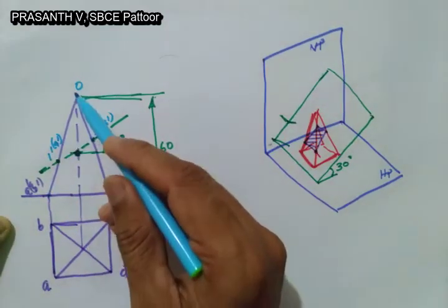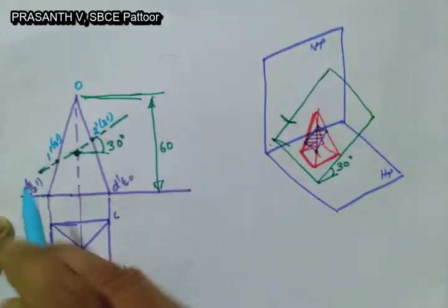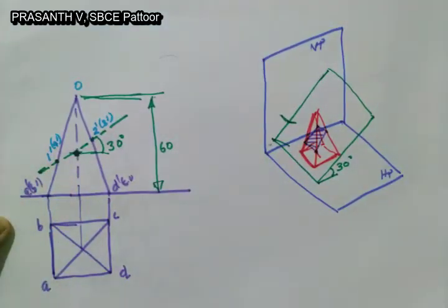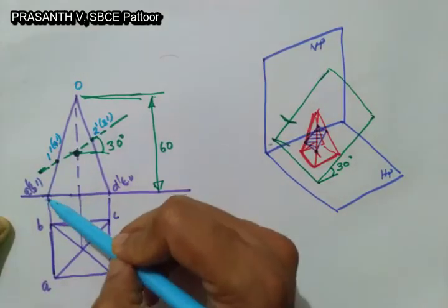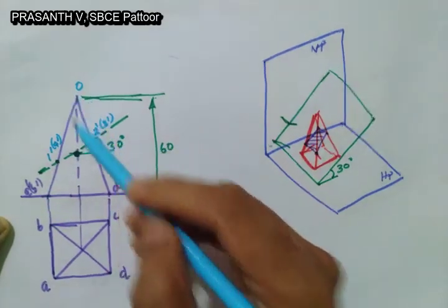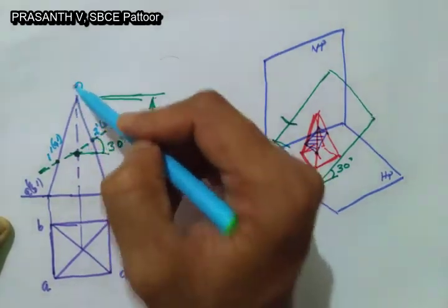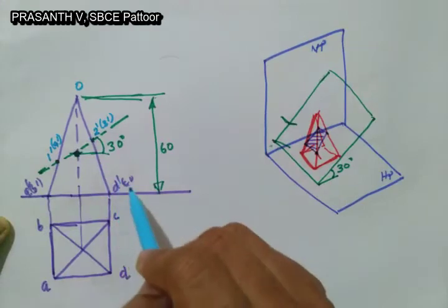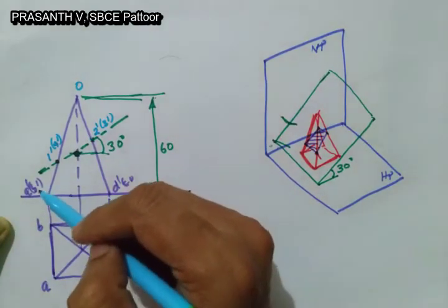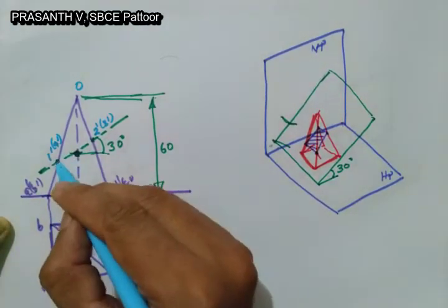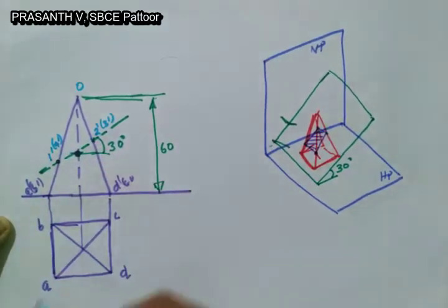This AO is the first visible line. Going from left to right, I am dimensioning it, putting the numbers. That's why from the left, AO is the first visible line. Then DO is a visible line. Behind DO we have CO. Then again we have BO. Let's say 1, 2, 3, again 4 here.